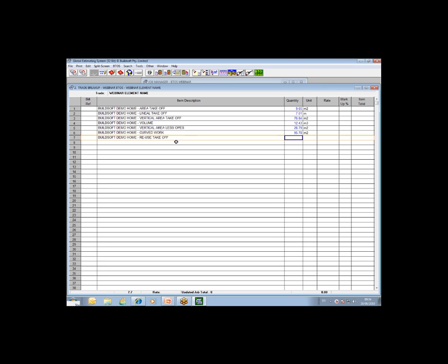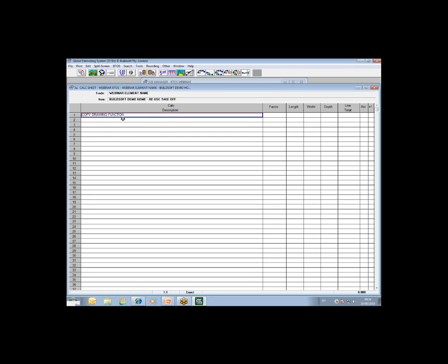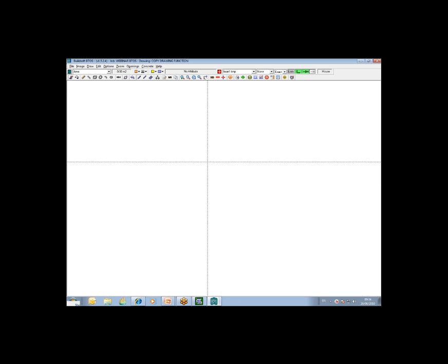So I'll give you an example of that. This last option here is reuse takeoff. Double click, and the function itself is called the copy drawing function. So what I'm going to do is, as before, activate the BTOS module into the drawing screen. And what I want to do is return, let's say, the lineal meters of the study. So I go to my status bar and I change my takeoff type to lineal meters. Of course, I can come along and change my line color and line thickness.